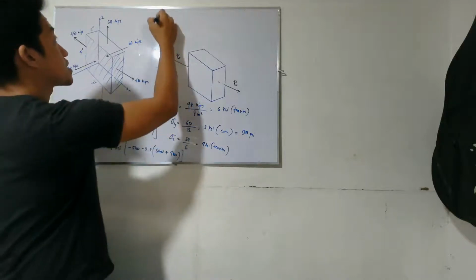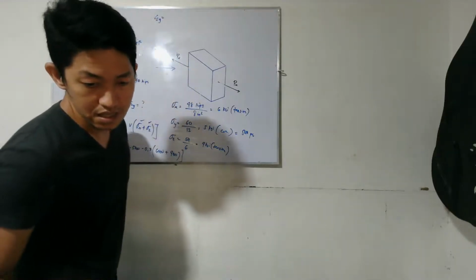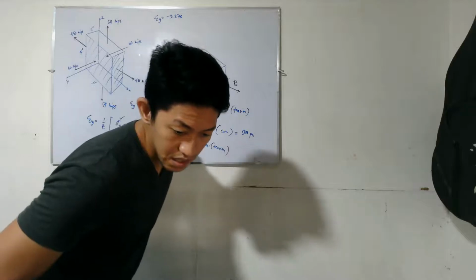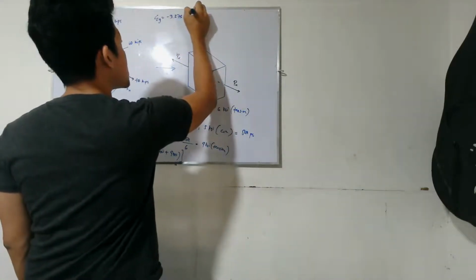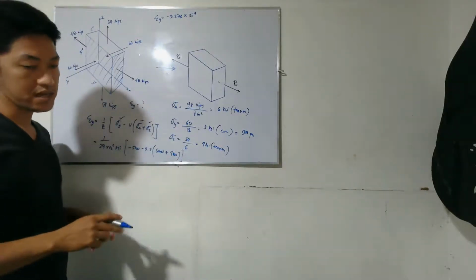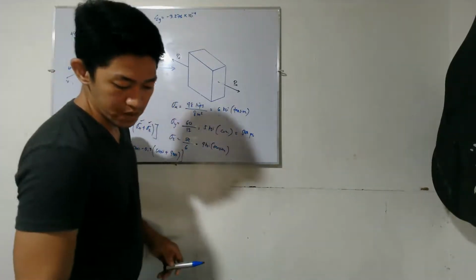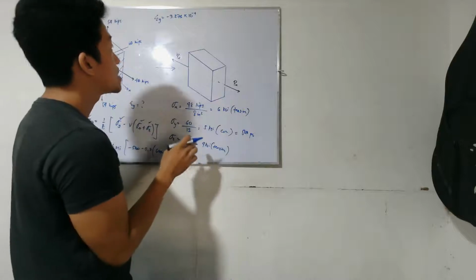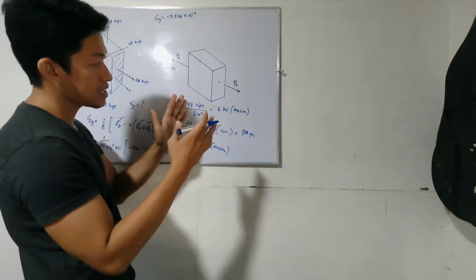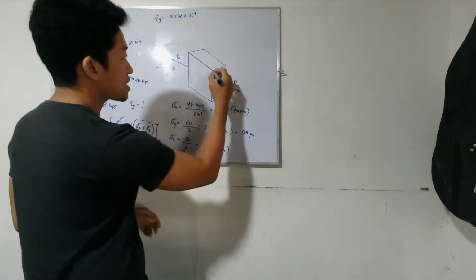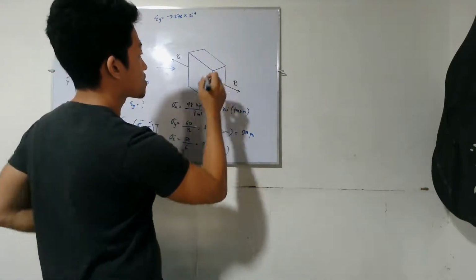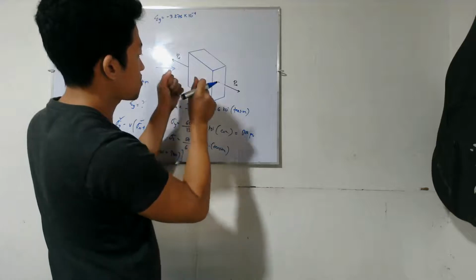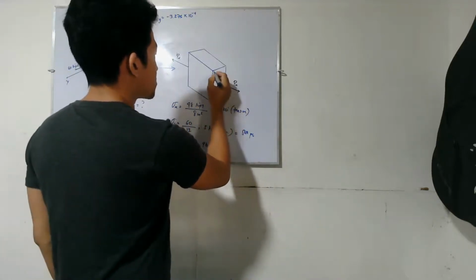Therefore, the strain in the Y direction is negative 3.276 times 10 to the negative 4. The strain has no unit. So we now have the strain. The value is negative, meaning the Y dimension shortens. When you stretch in X, the Y becomes smaller.